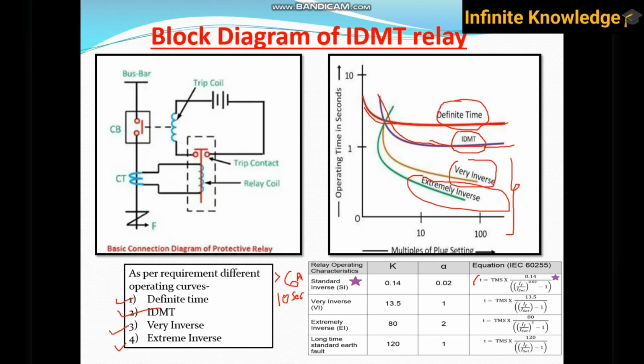In most industry we go with the IDMT characteristic, and there are some formulas also. You can calculate the time to trip. If I use a 6 ampere MCB and my running current is 10 ampere, my load is taking higher current and my set current is 6 ampere. By these two values we need to put in the formula. IF means fault current, so fault current is 10 ampere, and the set current is 6, raised to 0.02, minus 1, into 0.4.